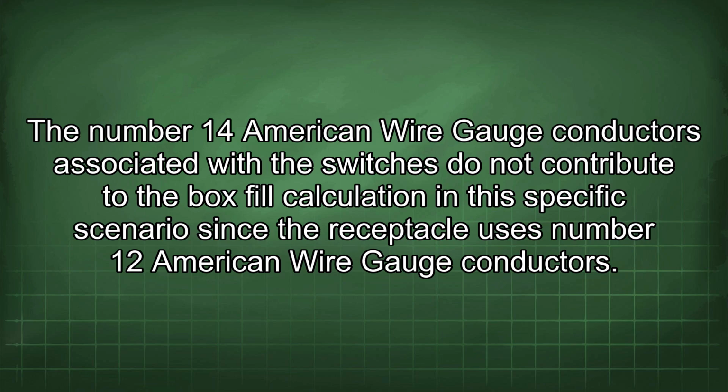The number 14 American wire gauge conductors associated with the switches do not contribute to the box fill calculation in this specific scenario, since the receptacle uses number 12 American wire gauge conductors.